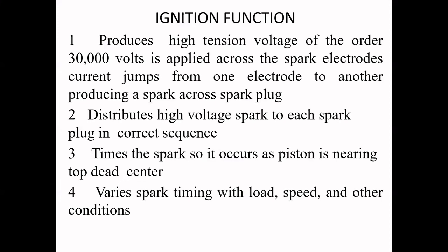But in actual practice, we design the engine in such a way that the spark occurs as the piston is nearing top dead center. That means the spark has to be produced before the piston reaches the top dead center position. This is very important. The timing and occurrence of the spark play a very important role as far as the ignition system is concerned.